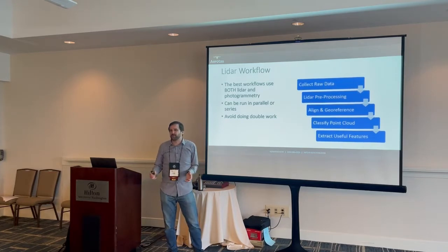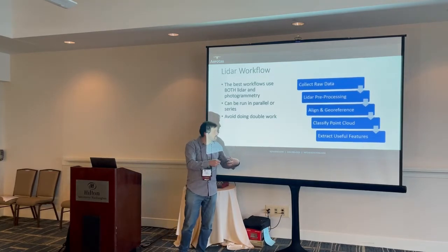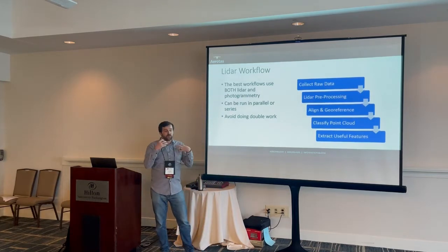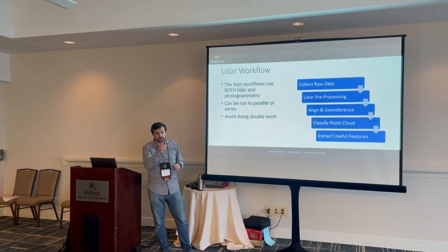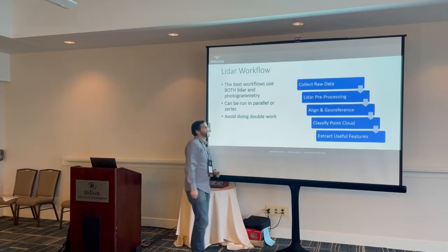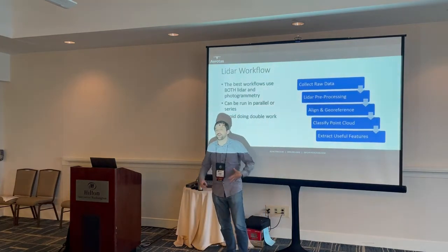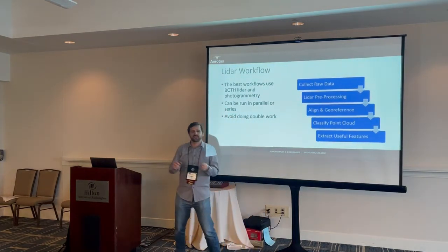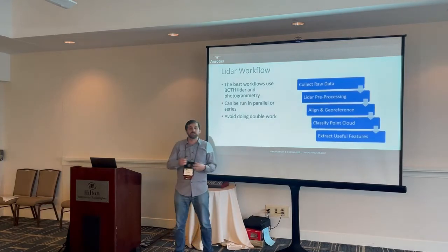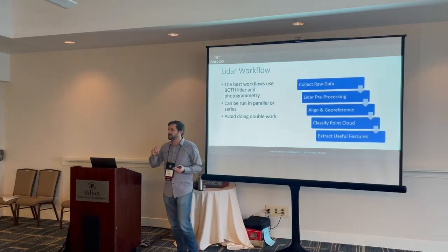What they care about are useful features. So you have to go from that full resolution point cloud, even once it's fully classified, if it's fully classified, which, as I will talk about, you don't have to do. But if it is fully classified, you still then have to extract your useful features. You have to turn those hundreds of millions of ground points into a TIN surface. You have to turn those buildings into building footprints, roof drip lines,